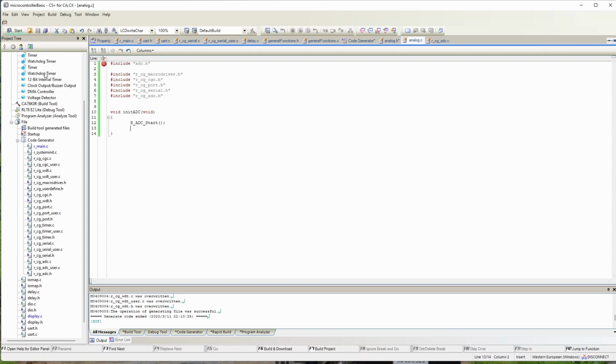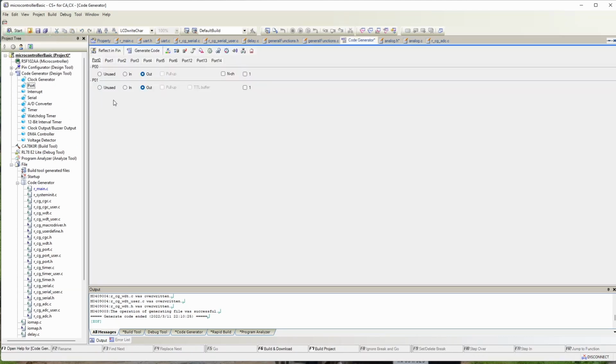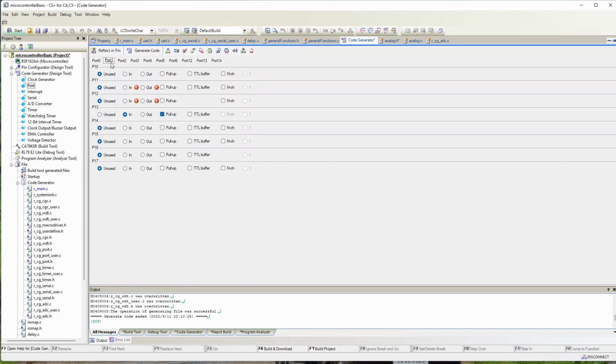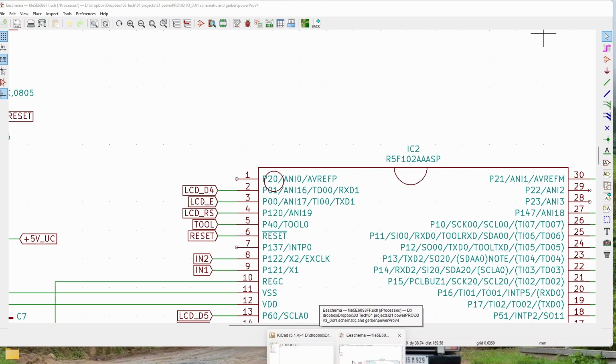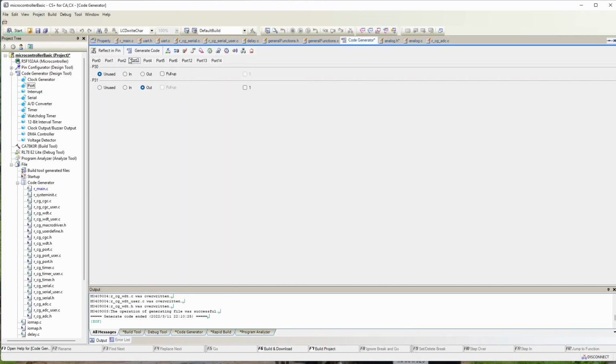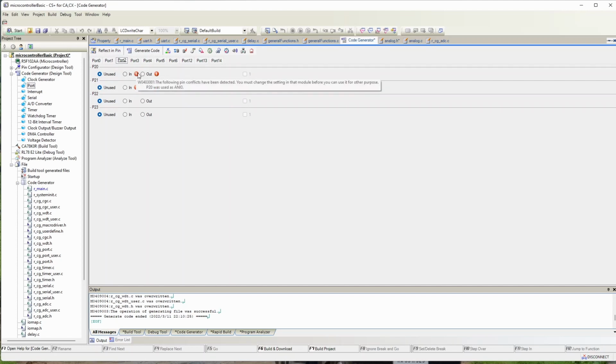And if you go to ports and see, this would have automatically become, I think, whichever port we were connected to. It will show in the port, that is P2.1, port 2.1. So it is telling it is used in analog. You don't have to set it as input or output, the driver will just do it by itself.